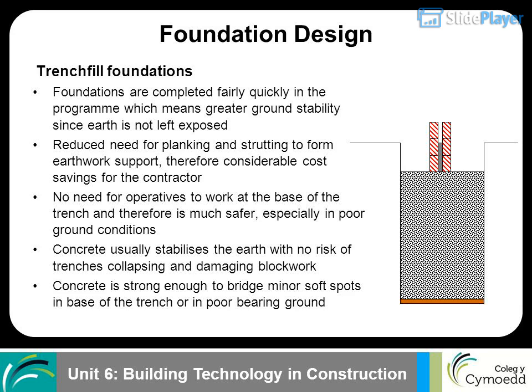Concrete usually stabilizes the earth with no risk of trenches collapsing and damaging blockwork. Concrete is strong enough to bridge minor soft spots in the base of the trench or in poor bearing ground.